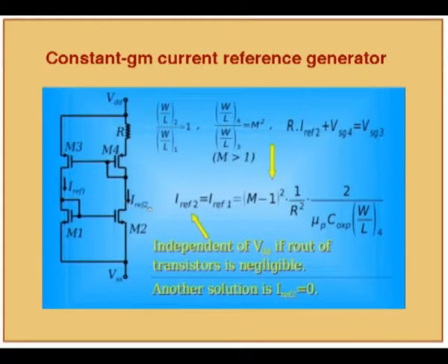Yes, there is. Suppose I reduce the drain current of a transistor without changing anything else, what do you expect to observe in the output impedance? If I reduce current, it will increase, right. So in an MOS transistor, if I reduce current, output impedance will increase.